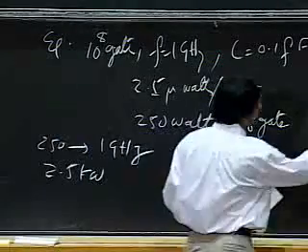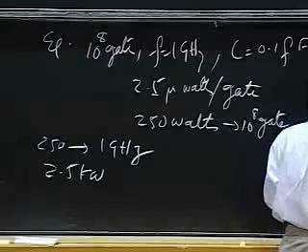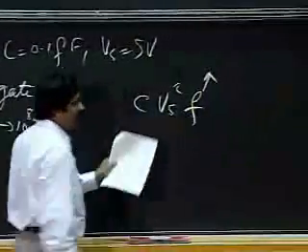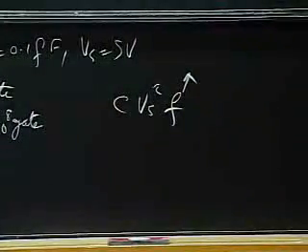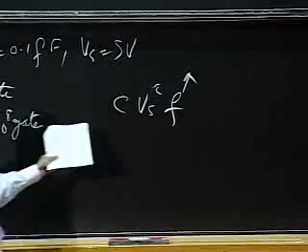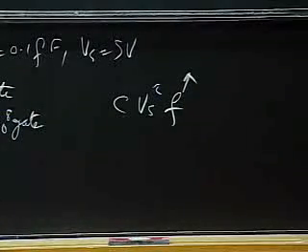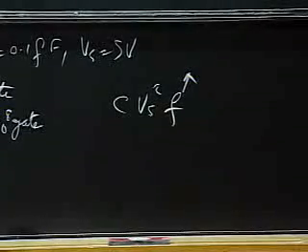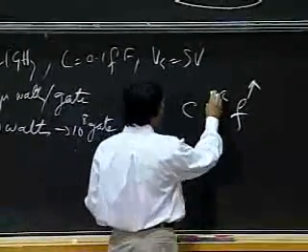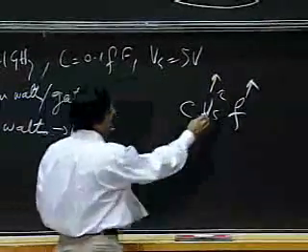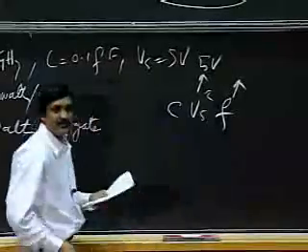If I stare at this equation, C Vs squared F, I want to increase F because people will buy computers if I have higher frequencies. Intel has managed to use its marketing campaigns to pretty much convince consumers that high frequencies are a good thing. Whether they really mean anything or not is a different issue. So we get this huge power, assuming 5 volts.